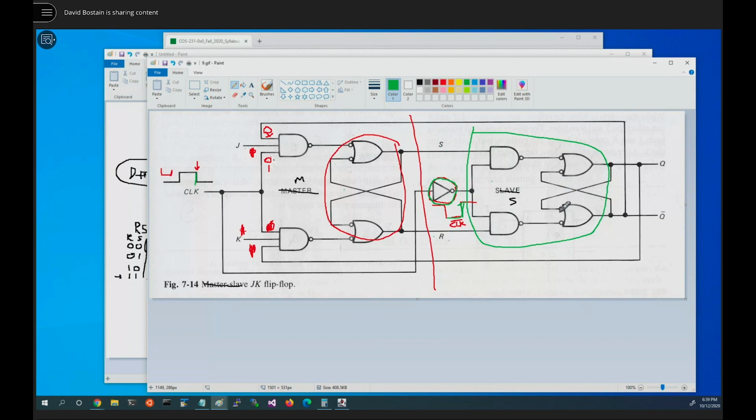We simply created a moment in time where we have that little sliver of I'm high and you're low, and we reverse it. And because of that, we can only snag things while on both of them the signal is high, but it's so small a time when they're presenting the correct signal that it works effectively the same as having done an edge trigger. Anybody have any questions about that?